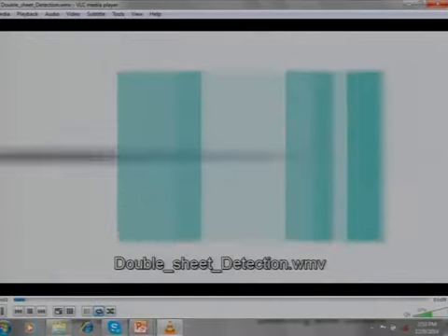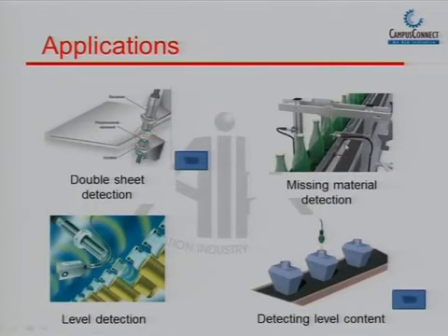On a commercial entity, the sensors are made for wide usage. So these through beam sensors, whatever the media, there is a bottom limit and a top limit of density. Sender and receiver are tuned or calibrated to the media they have to sense. The air gap here is the biggest attenuator. It is not the thickness, but the inclusion of the air gap that is the attenuating factor. So any air gap, due to whatever reason, is transgressing the physical aspect for which it is being designed. So the sensor might be working perfectly okay.